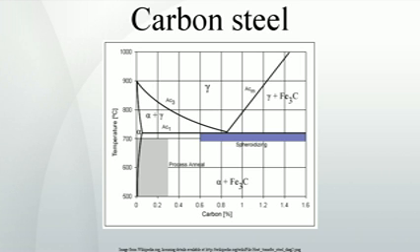Generally speaking, cooling swiftly will leave iron carbide finely dispersed and produce a fine-grained pearlite, until the Martensite critical temperature is reached, and cooling slowly will give a coarser pearlite. Cooling a hypoeutectoid steel, less than 0.77 wt% C, results in a lamellar pearlitic structure of iron carbide layers with a ferrite, pure iron, between.